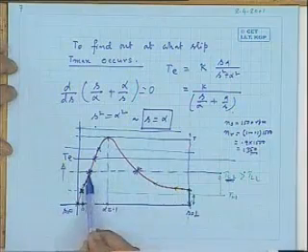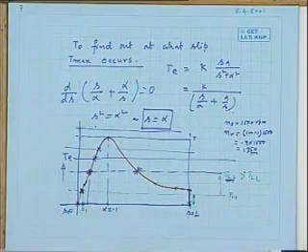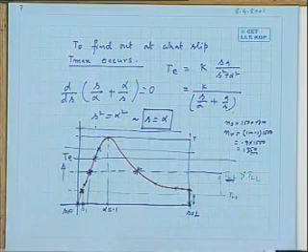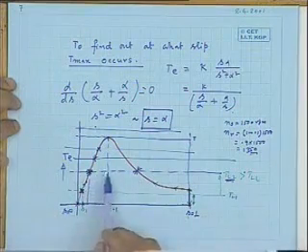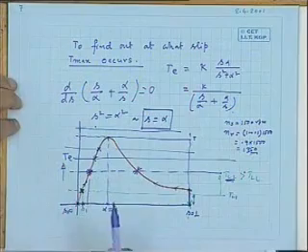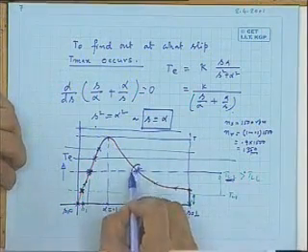So one should answer it like this: if this is the load torque, I should tell machine may operate at this slip or also at this slip. Is it not fair to tell that? Because at those 2 points, electromagnetic torque equals load torque, and machine may continue to run steadily at that RPM. Getting? So there are actually two operating points possible, at least as it appears right now.